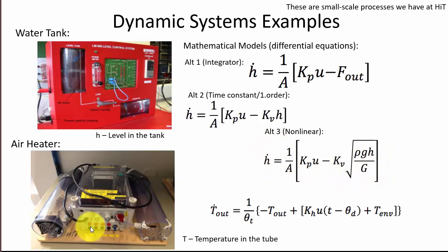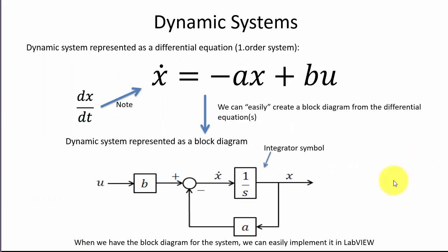Here is another small-scale process model called the air heater, and here you see the differential equation for that specific system. So these are the kind of equations we are going to implement in LabVIEW. In this video we are going to implement the differential equations as block diagrams.